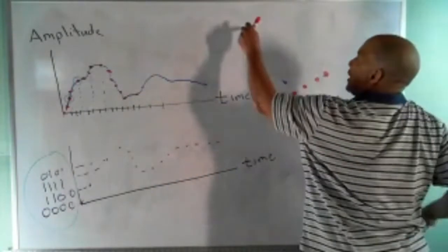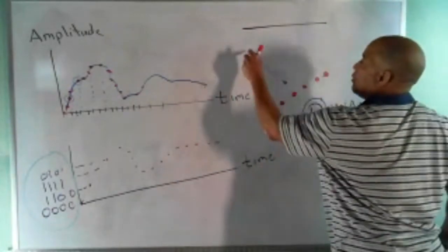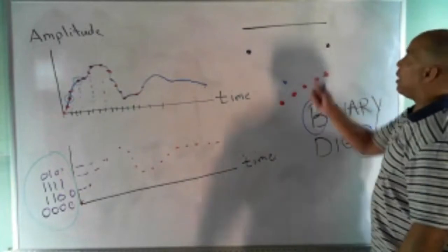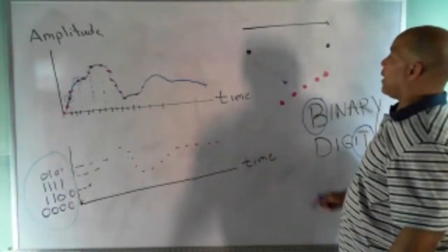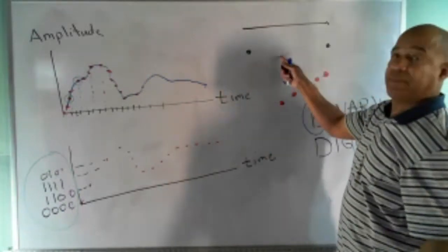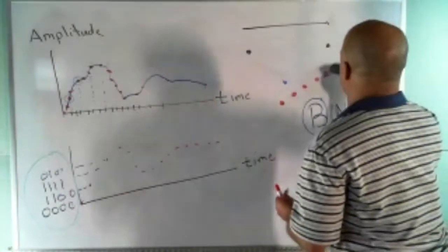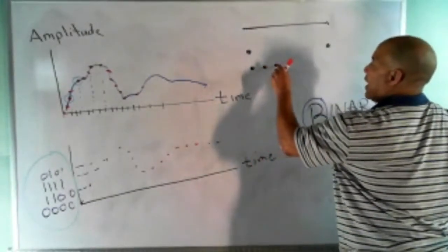So here's a line. But if I digitize that line, what I would do is take a sample and another sample. All the information in between this point and this point is thrown away. If I want a better representation of that line, I just sample at a higher rate, which means I'm going to represent that now with more dots. Maybe I got this number of dots.